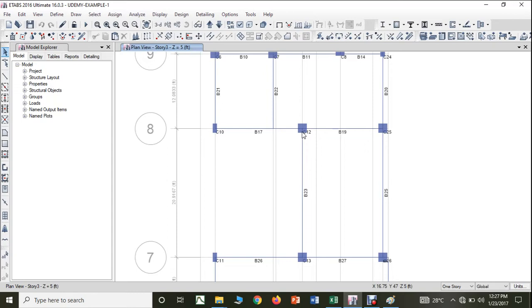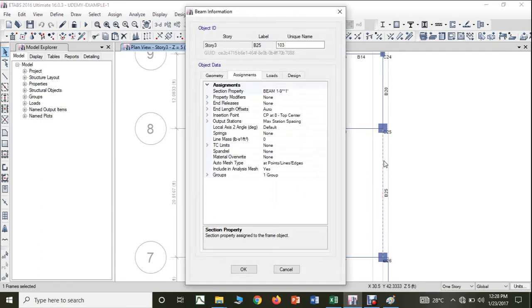Even though it looks like you can design it as an axially loaded column, uniaxially loaded column, we are supposed to do it as a biaxially loaded column. The reason is that the moments developed by this column and this column are going to nullify, but the moment developed by this beam will be very significant, because this entire area, of almost